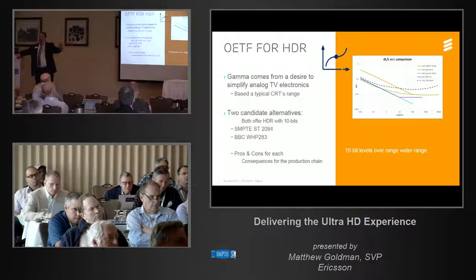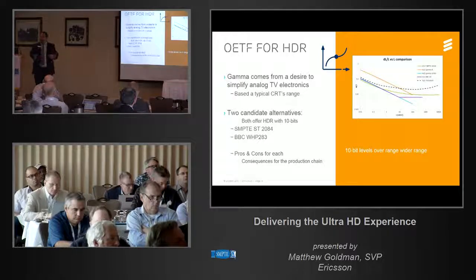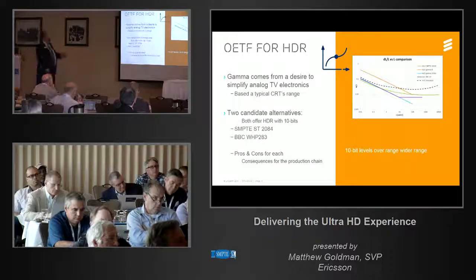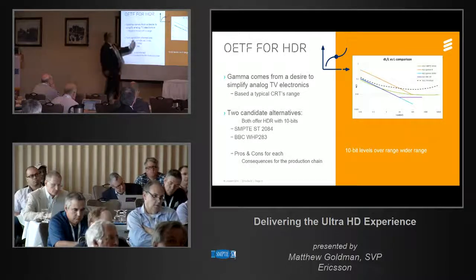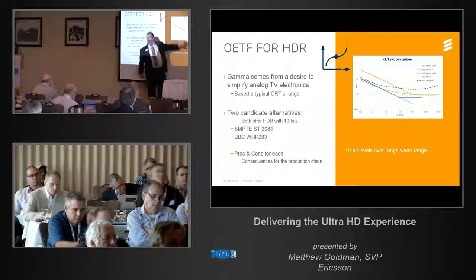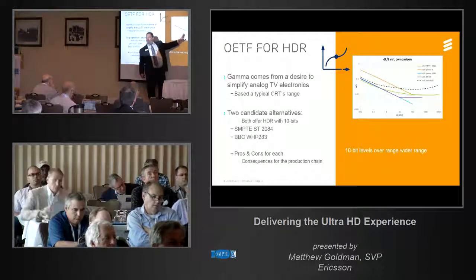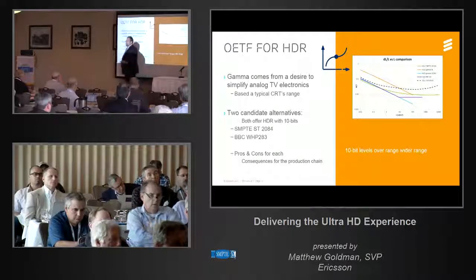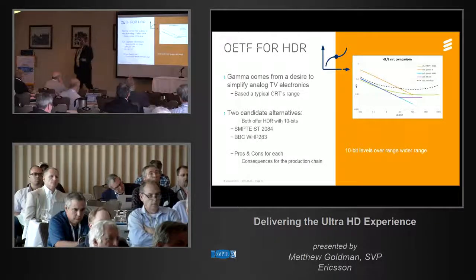So we have to make sure we define standards in HDR so everybody will look the same. We talked about the film earlier, about splicing. It's the same idea. If everybody does high dynamic range differently, there won't be any standards. But the point is that if I move this up, 10-bit looks great here at 100 nits. At about 2800 nits, if I slid this forward, it would look just as bad as 8 bits, even at 10 bits. The curve doesn't work right for that. So we need other curves.